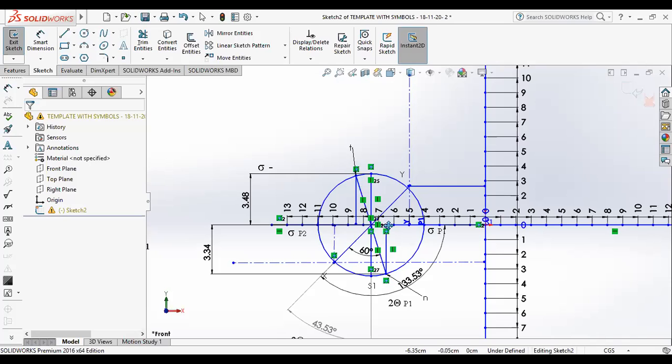How do we find them? Draw a vertical. Since the sigma axis consists of only normal stress, this indicates sigma x dash. Similarly, when I draw a vertical, this gives sigma y dash. This is normal stress. Since only normal stress exists here, on the Mohr circle this gives a principal stress, but this is not the maximum stress. This axis is only for sigma, this gives sigma x and this sigma y, and this length gives your tau dash.